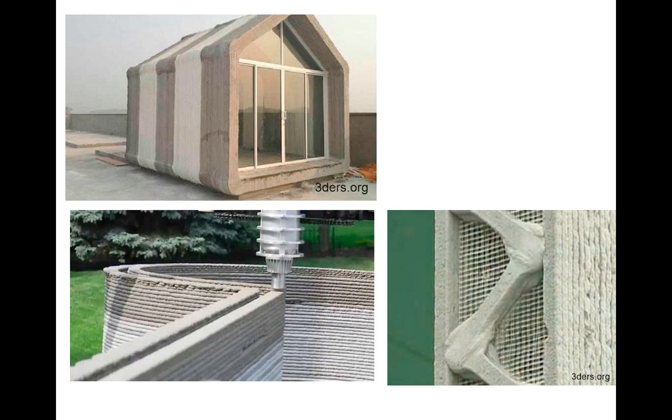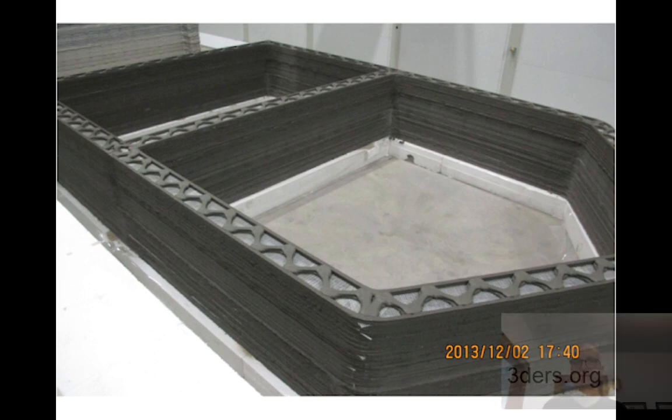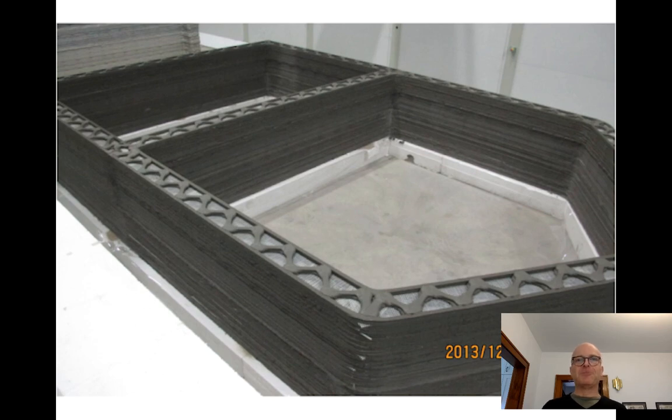You can see from these early examples that the process is pretty imprecise, right? Not maybe as perfect or as beautiful as we would like. And you can see too that there are some limitations. Usually these days, 3D printing in concrete has been done in the lab, so it's been used to make components. And transferring that precise mechanical technology out into the real world, where again, just like in other concrete construction, we have constraints that have to do with temperature and humidity. We'd like to pour concrete in pretty good weather. And the material being that finicky, that subject to changes in temperature or humidity, we're finding that digitally printing a concrete structure has difficulties in the real world, just like manually putting together a concrete structure.